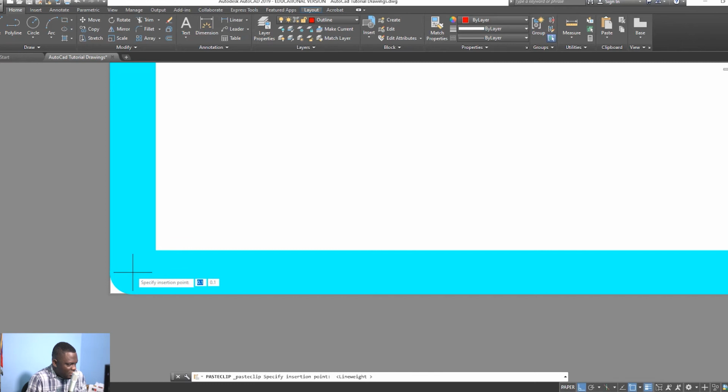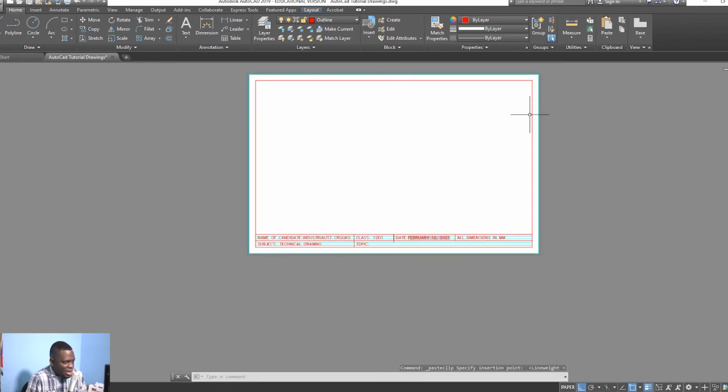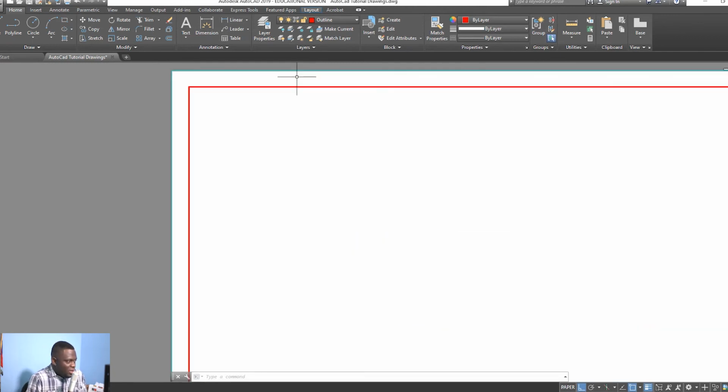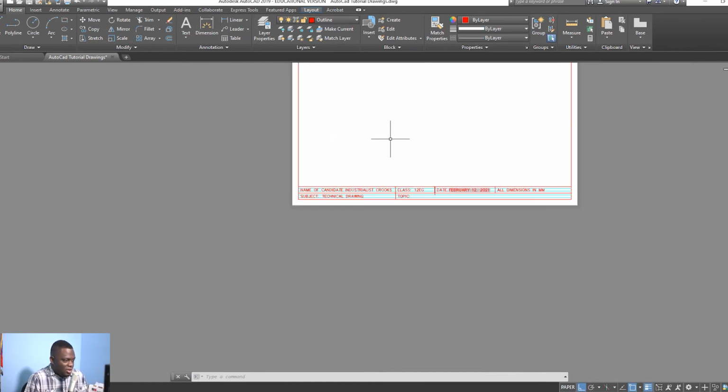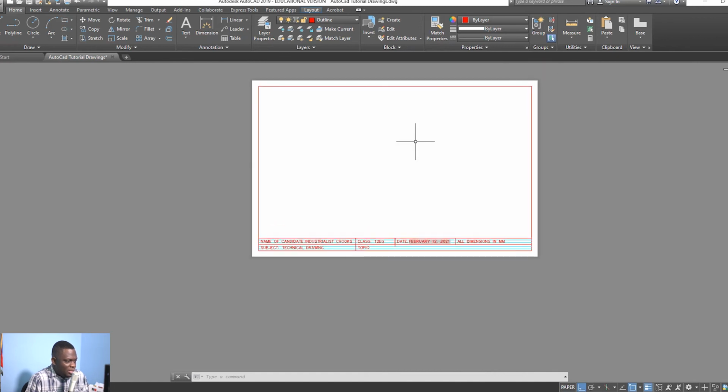So you can see that I'm matching the paper directly there, and I click, and then basically my title block is fitting the paper. Then from here now, all I have to do is remember to delete the lines, because some printers do print outside the margin, or they print much larger papers than 11 by 17, so you'll be able to see those lines. So you delete that, and there you basically have it. Your paper is set up to actually accommodate your drawings.